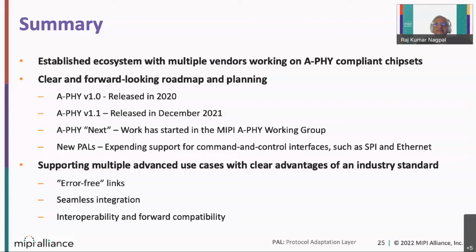The first question we received is about how a packet error rate of 10 to the minus 19 translates to bit error rate under harsh environment. Okay. So basically, Profile 2 of A-PHY is supporting PAM-X. So it is a baud rate, so it is a symbol. If I talk of PAM16, you get 4 bits per symbol. Okay. So your baud rate is